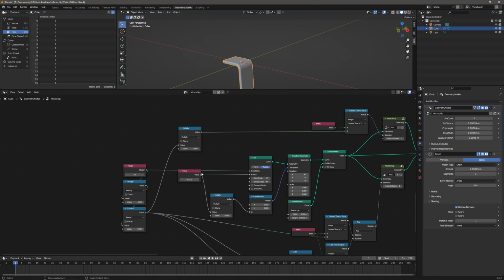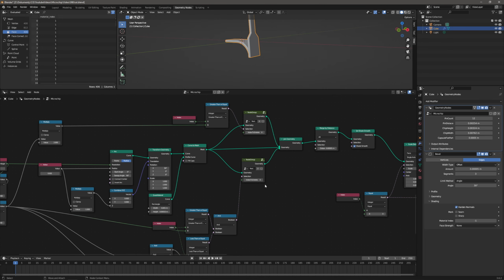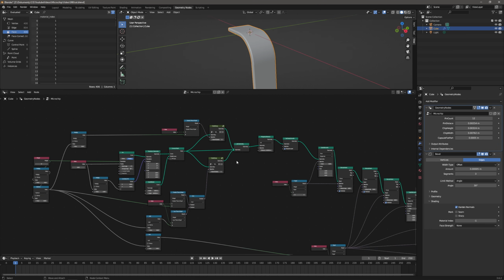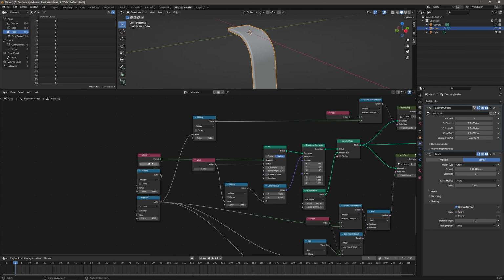This happens sometimes also when you change the radius of the arc. So let's change it to 1 millimeter. And actually here it stays the same, but if we go to a lower value like 12, we have to adjust the deleted faces again. But it works. It's definitely a working solution. So let's keep the resolution at 12 and the radius at 0.25 millimeters. And now really the pin is finished.